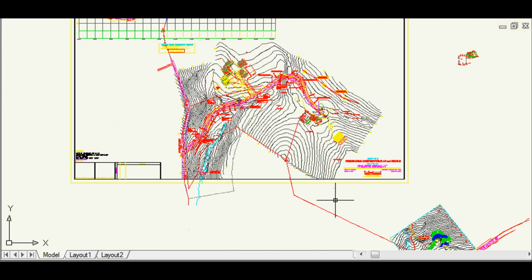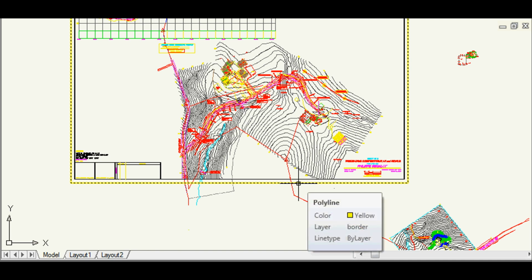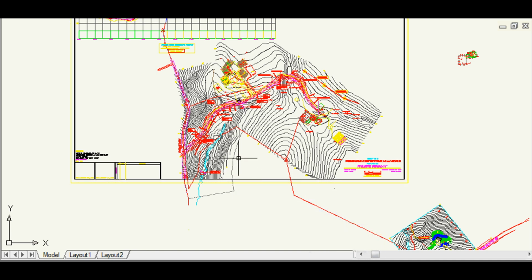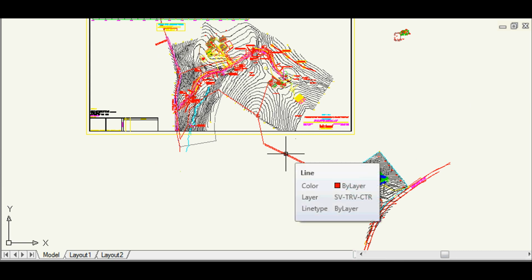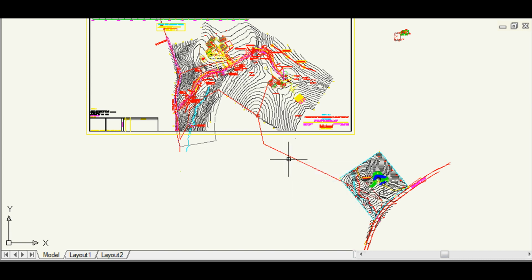This was quite a project we did, and I think I have some other video footage of this around, and maybe over time I'll dig that out and share it. But I just want to give a good explanation of baseline and how it works in surveying so you can have a better perspective. So this is an open leg baseline. Usually we would run a closed loop baseline, and I will dig up and show you an example of that. Because typically a closed loop will give you a much better connection. I'll explain that.